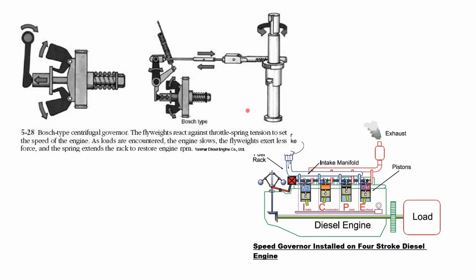The reason is, even though we have an injector pump separately, once we increase the capacity of the engine, like large engines, even prime mover sort of heavy vehicle engines, they do not need a separate injector pump. Instead, they have injector elements fixed on top of the camshaft in the engine block or head.